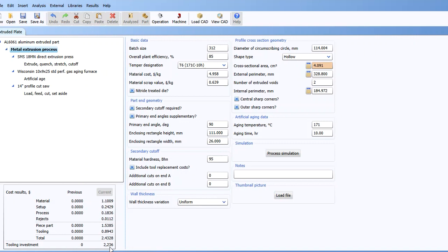I can get a reasonable idea of a part's cost just by specifying a life volume, importing a CAD model, picking a manufacturing process and a manufacturing location, and then specifying a part material. Next, I'm going to go through all of these primary cost drivers, and I'm going to make any modifications that I think might be needed. Basically I'm going to refine that initial cost estimate.